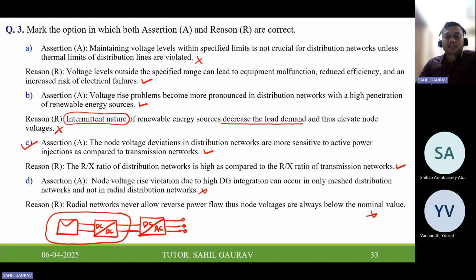Generally they are used for improving the power quality. So inside the inverter we will include UPQC or DSTATCOM like this. You just explore. But I can say this can provide ancillary services like unity power factor, improved voltage, improved power quality.